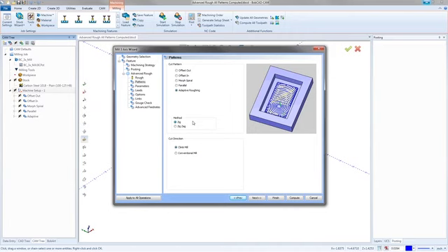So I don't remember what I put in. I'm either doing a 1 inch depth of cut with a 50 thou step over, so a 10% step over, or I might have done a 1/2 inch cut. It's on the other one over there. We'll look at it in a minute.